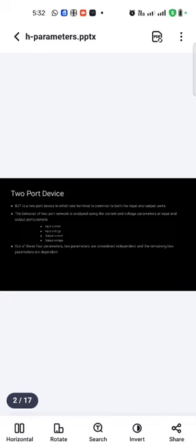For BJT amplifiers, some biasing resistors are used. For what purpose are we using these biasing resistors? In order to operate the transistor in the active region, at the Q point or the fixed point. If it is not fixed, it goes into the saturation region or the cutoff region. If it shifts to saturation or cutoff region, we may get clipped output. That's why biasing is needed.